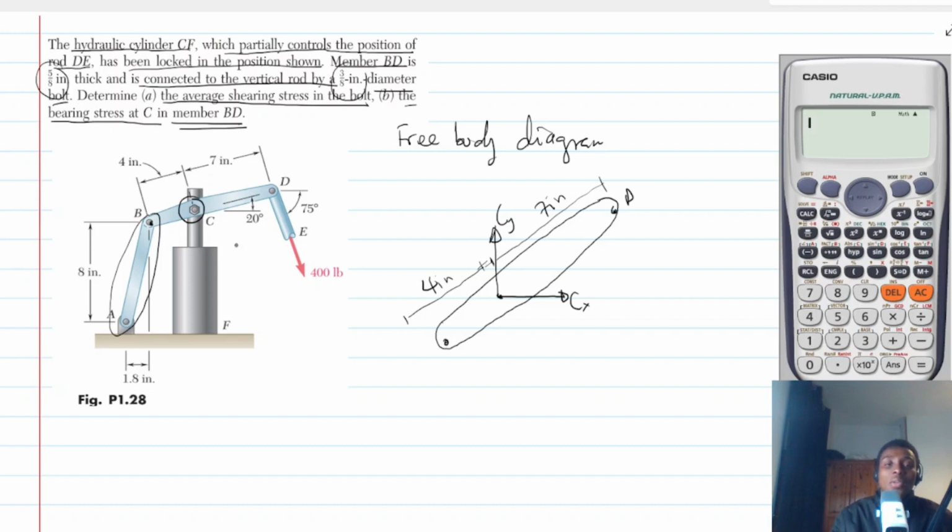So basically, we can look at this as just a force which is in this direction. Okay, so it's a two-force member. That's what we are trying to say. So we can label the force in that AB with just this.